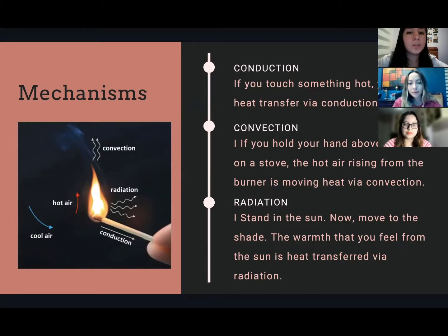Convection implies how energy enters or leaves the control volume by analyzing the mass fluxes that are crossing the surface. In the case of conduction, it is a heat transfer process based on direct contact between bodies, without exchange of mass. Molecular excitation is passed between the molecules of the control volume and the surroundings. It is quantified by the heat flux vector, and the direction occurs along with the temperature changes.